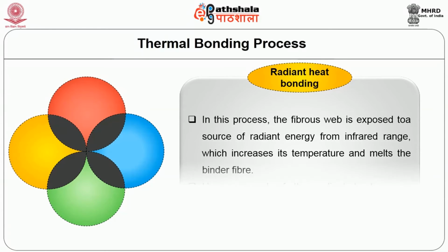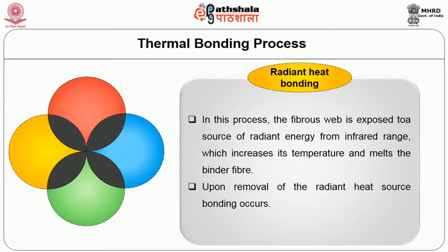The radiant heat bonding. In this process, the fibrous web is exposed to a source of radiant energy from the infrared range, which increases its temperature and melts the binder fibers. Upon removal of the radiant heat source, bonding occurs.